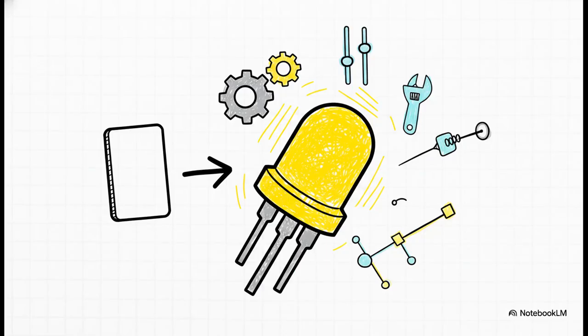But what if the library doesn't have that highly specific component you're looking for? Are you stuck? No way! I was genuinely amazed by this. You can use a SPICE directive. This means you can literally paste custom code directly onto your schematic to modify the core physics.